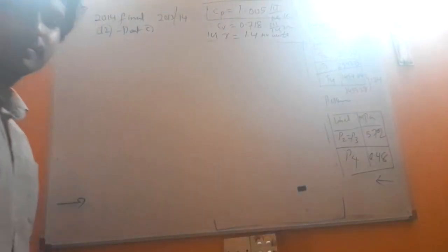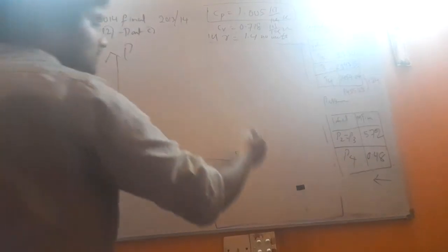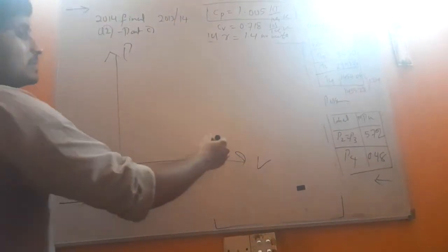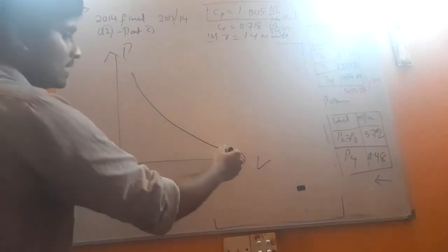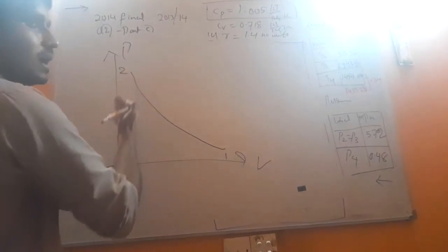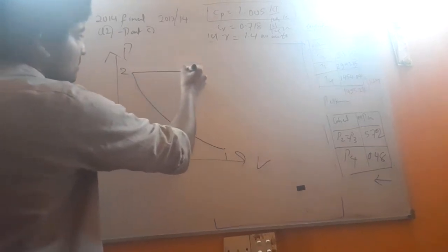So with me, tell me the PV diagram, diesel cycle. Reversible adiabatic, or in other words isentropic compression, 1 to 2, you are going to compress. How? Adiabatically, but reversible. 2 to 3 at constant pressure you add in some heat.